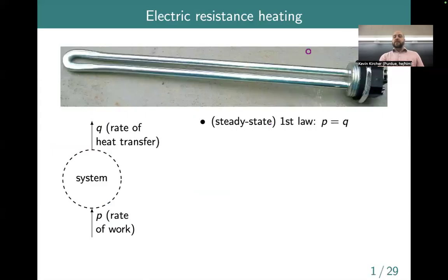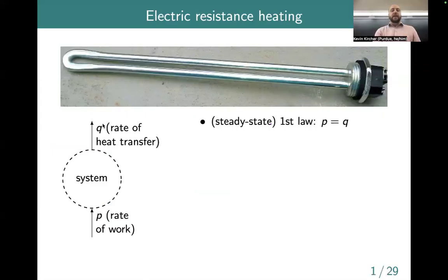Okay, so let's start out by talking about kind of the simplest form of heating with electricity, which is just electric resistance heat. So very simple. Basically, this thing here is just a hunk of metal, typically maybe something like a nickel chromium alloy. So particularly, carefully chosen metals, but basically just metals. They might have a ceramic core, or it might be metal all the way through.